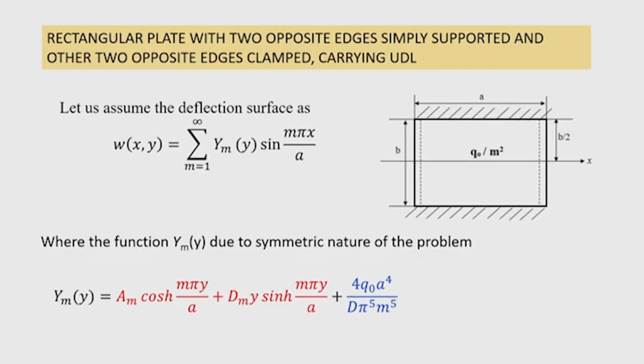Then we have the reinforced concrete slab, where the slab is supported by a beam which is integrally built, that means monolithically cast. Therefore, a fixed condition develops at the end. So, fixed conditions are common and we cannot ignore them, and with the help of Levy's method we can easily handle this condition.